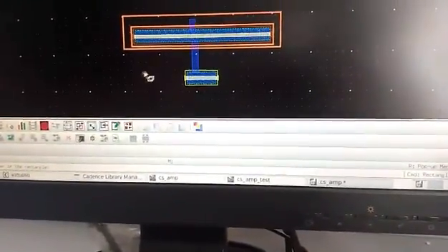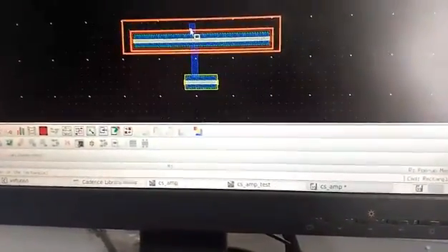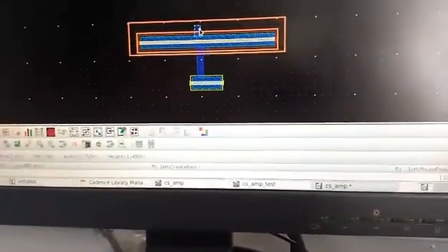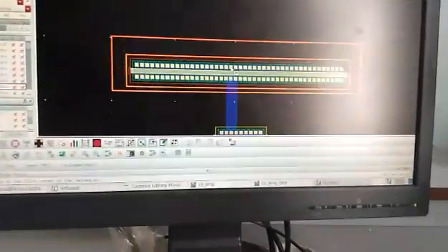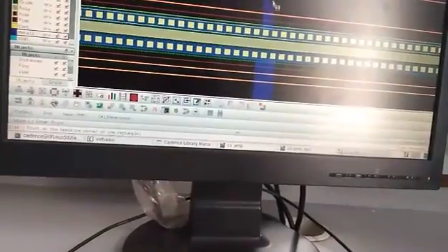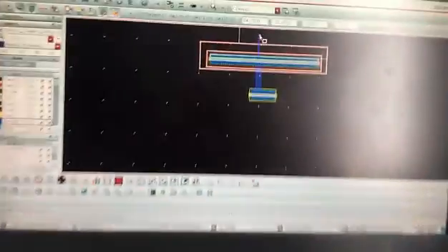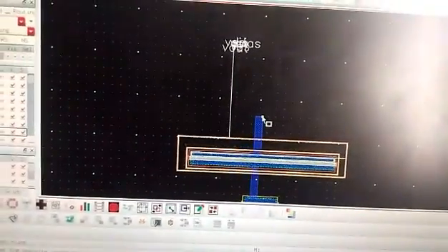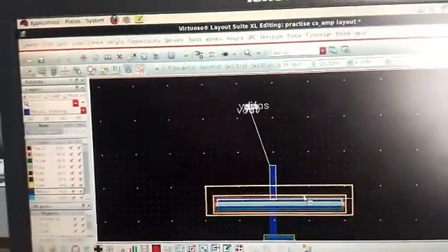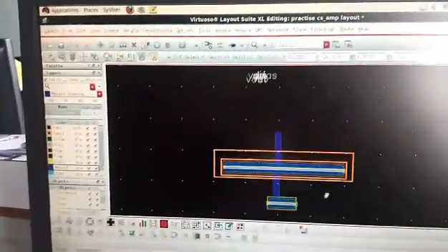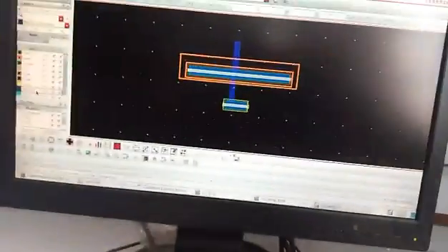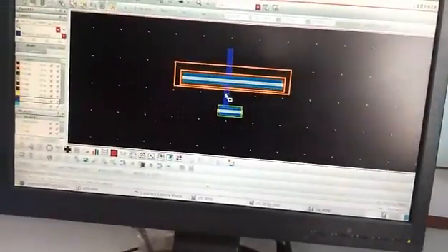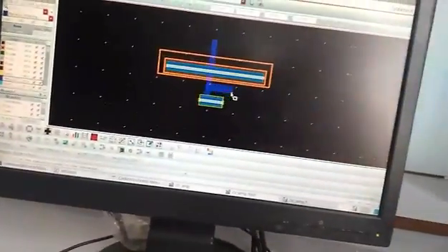Okay, I'll be skipping a few steps here and going directly to the complete, finished and saved layout, instead of showing you the connection and wasting more time. Another point to be noted: I have seen some people draw an unnecessary line from the output too, which is not necessary. You can always place the VDD directly into the metal line. Yeah, there we go. That line is actually not needed.